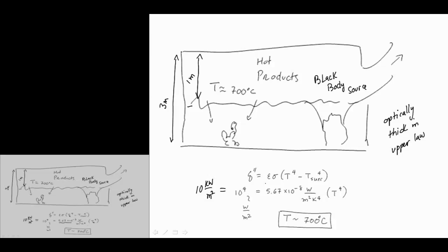So once we reach these types of temperatures, this is what we think about in fire as being representative of what's called a flashover condition. I think we've discussed this before, but flashover refers to the process where we have full involvement of the room because the heat fluxes are able to ignite fuel packages away from the fire. So the direct fire heat flux, Q direct, is much smaller than Q upper layer.